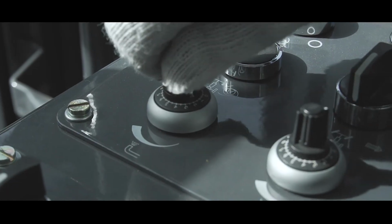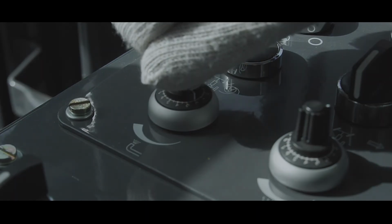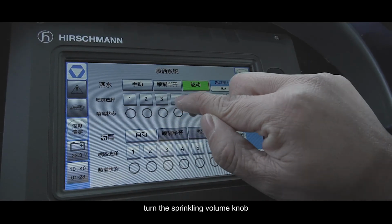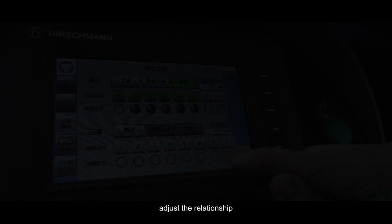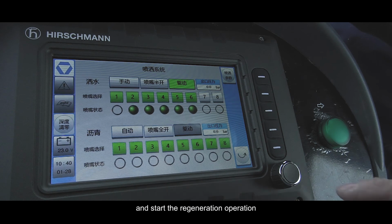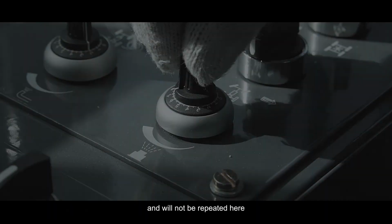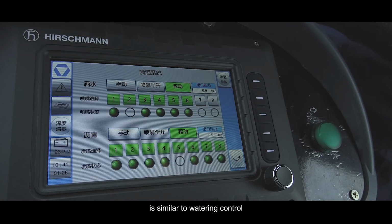In the manual state, the amount of water sprinkled is realized by adjusting the potentiometer. Turn the sprinkling volume knob to the maximum state. After the water is sucked into the rotor housing, turn the sprinkling volume knob to the minimum state. Then, adjust the relationship between the vehicle speed and the sprinkling volume and start the regeneration operation. The process of stopping is completely opposite to the above process and will not be repeated here. Emulsified asphalt spraying control is similar to watering control.